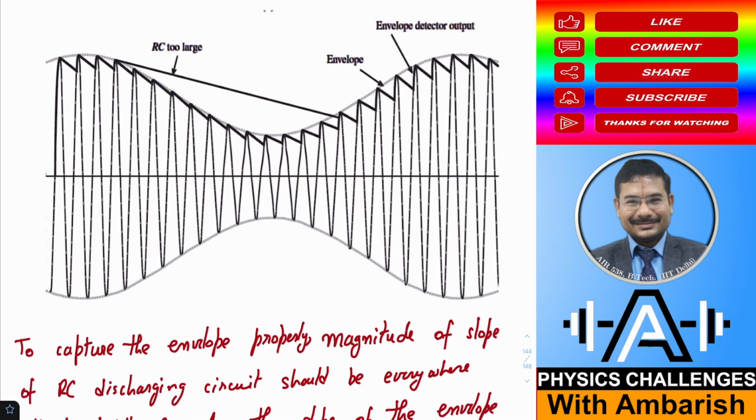A little bit of digging is fine, but it cannot go above the peaks, otherwise I'll be missing the peaks, right? Therefore the slope of this RC discharging should be greater than the slope of the envelope itself, because the peak to peak portion of the graph has the same slope as the envelope. So I want the slope of the RC discharging circuit to be slightly greater than the slope of the envelope, so that I can dig a little below the peak. Too much digging is also not good, because if it digs too much below the peak, then I do not know where the peak is. So again the message is lost. I want it to dig as little as possible below the peak, but it should not pass above any peak, so as to accurately recover the message signal, right?